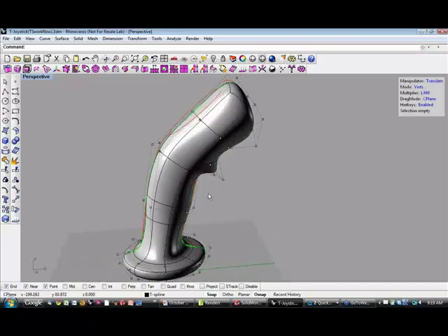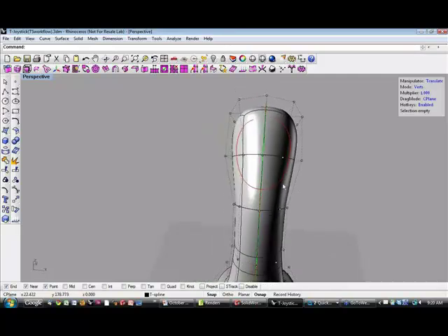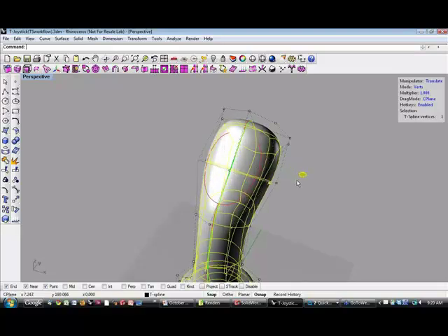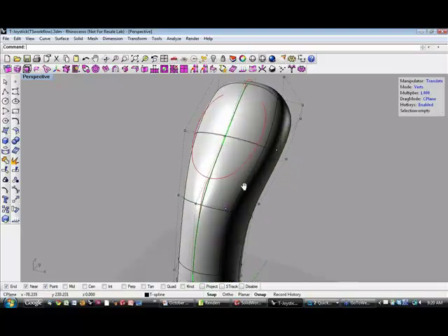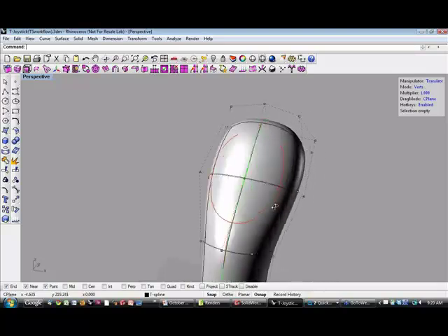We will add two more parts of detail before we bring this model into SolidWorks. First of all, we need to have a hole here in our model because this is where the plate will go on for the joystick. And if you want a hole in T-Splines, you have two options. First of all, you can just trim the T-Splines model using the Rhino trim command, and it will turn into a NURBS, but you'll get an exact trim. And that's often a good approach, but when you do that, then your model is no longer a T-spline. The second thing that you can do is just delete T-Splines faces. So that's what we'll do here.